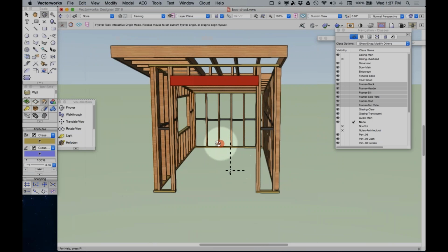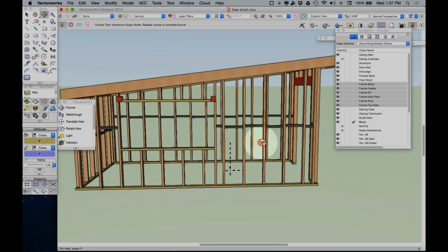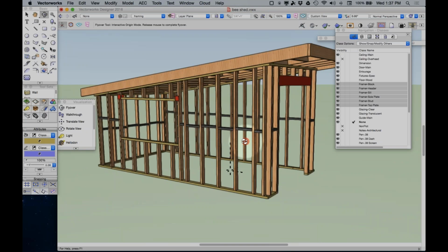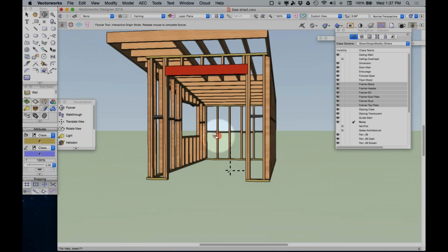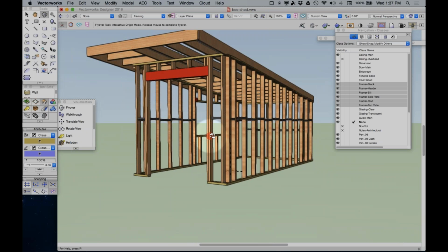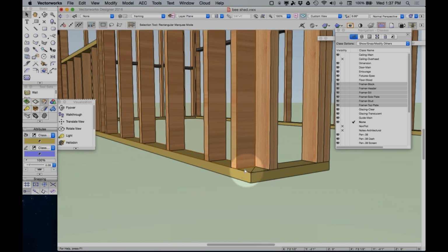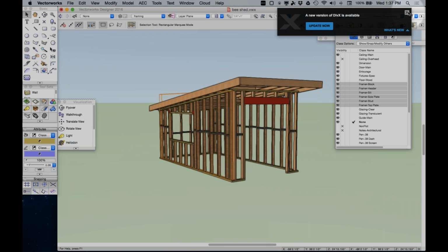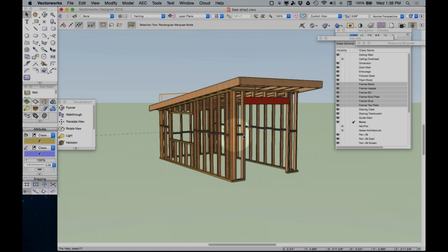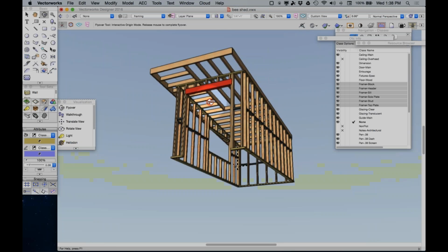You can see that just for fun, I've assigned some textures to it. Now I wanted to do some advanced framing, so in some cases I've by hand modified some conditions. I removed an extra stud to give myself a 2-stud corner here, and have adjusted the model accordingly, right? And you can see that the roof is also framed, so let's go back and look at that.